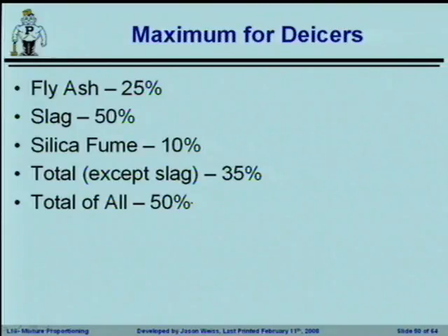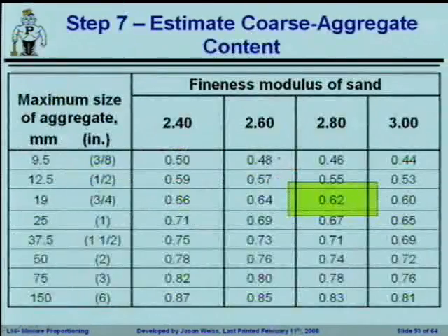Now, why would slag be excluded from our fourth line down? Similar to cement, because it's the difference between hydraulic and pozzolanic. Exactly. Fly ash and silica fume are going to be much more pozzolanic, so they are not going to react simply on their own with water. They need to have the calcium hydroxide in the system. And if you get above about a third of the system, you're just going to simply run out of calcium hydroxide. So we typically want to limit those. We can go a little bit higher if we're adding slag in because it has its own hydraulic properties.